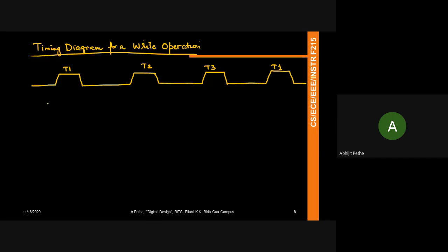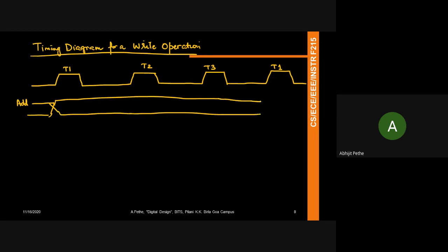So what I would do in this case is, at the start of T1, I will ensure that, if I look at my address, my address is valid throughout this entire period of writing. So again, you guys have done Verilog to know that these indicate that signal transitions, right? So this point, I'm saying this address is valid on the address lines. So when address is valid, and then what I'm going to do is I'm going to enable the memory.